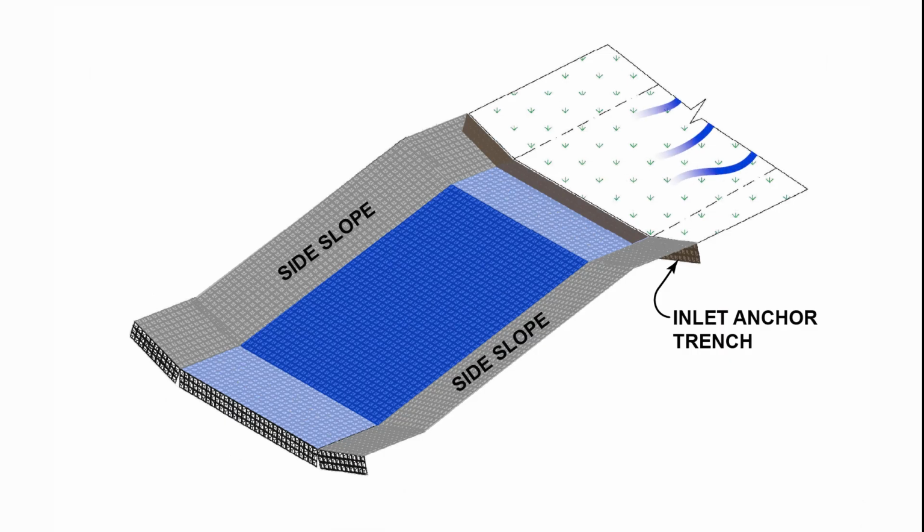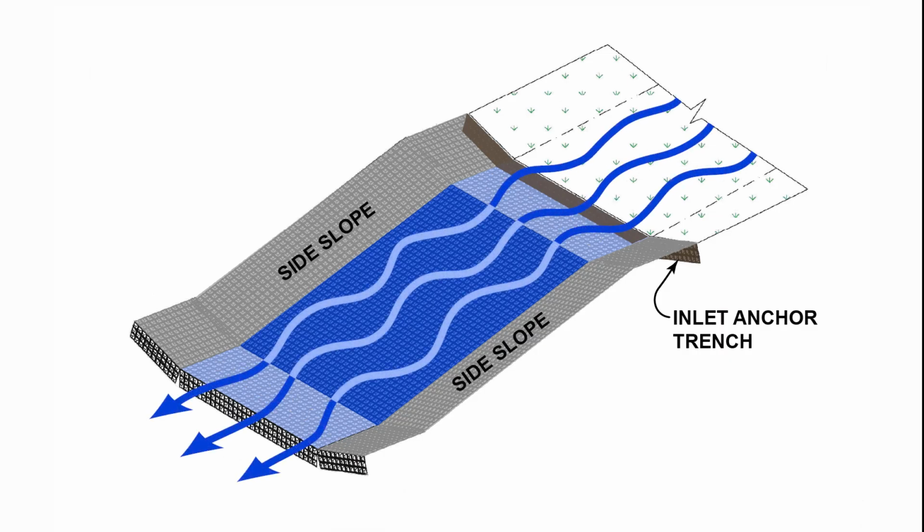Water will flow from the grass waterways into and down the chute. This is essentially a controlled overfall where fast-moving, concentrated storm flow would otherwise erode bare, unprotected soil. The tied concrete block mat also protects the side slopes to ensure that the entire flow is carried on the mat surface and does not come into direct contact with the soil.